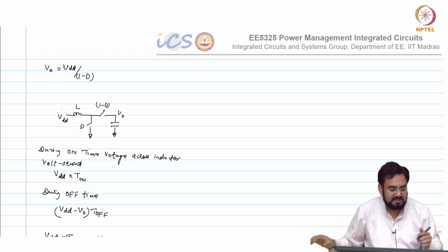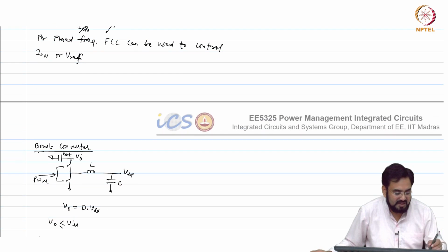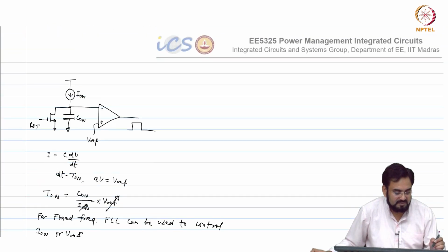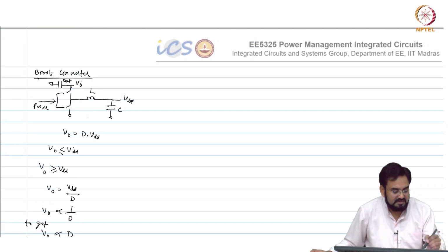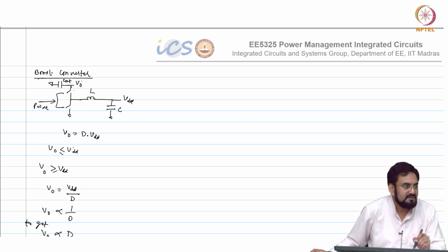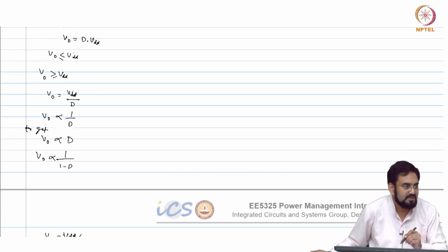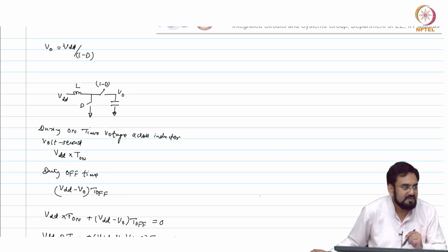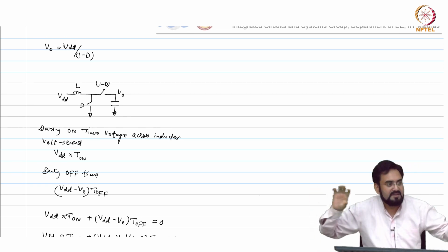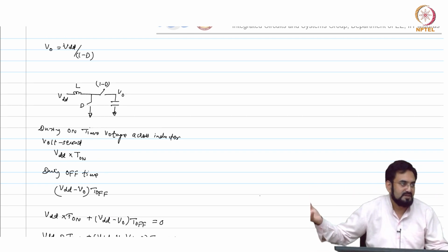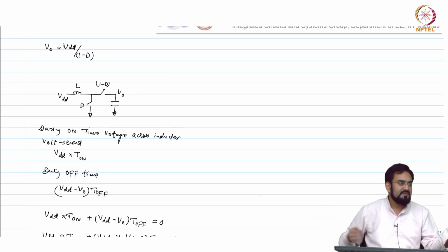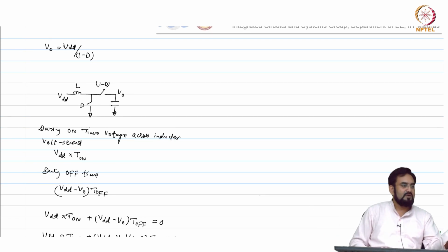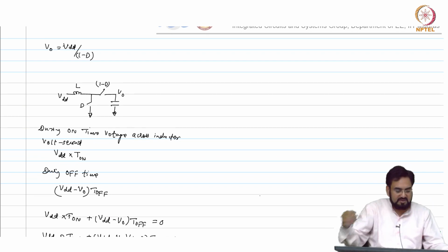So in the buck, I mean this is your buck, left side is your buck if this is connected to input, right side is your output, and if you have a switch at the output side, then it becomes boost. Now you have a switch on both the sides and you operate only 2 switches at a time depending upon whether you want to configure in a buck or boost mode, and that becomes a buck boost actually, 4 switch. So we will talk about that later.